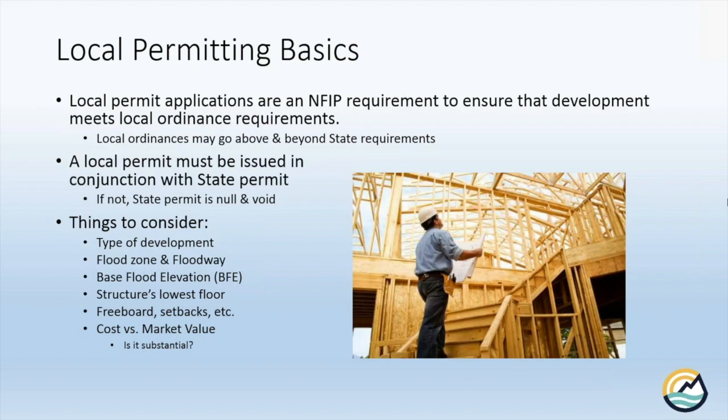You need to consider what flood zone we're in, and are we in the floodway, yes or no? If you are, certain things apply. What's our flood elevation? How high do we expect that water to get? Once we know that, how high is the lowest floor on that building? Again, the requirement is you've got to be high and dry. Are there any local, higher standards? Do we have freeboard? Do we have setback requirements? Things like that. We need to consider those.